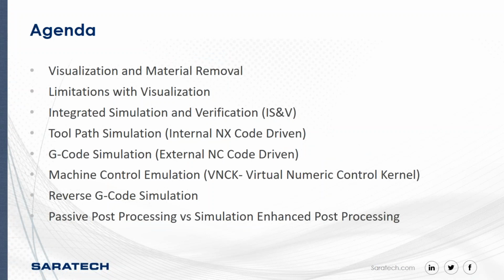We're going to go through visualization and material removal, limitations with visualization, the integrated simulation and verification, which is called ISNV, the toolpath simulation, which is the internal NX code. That is the CLFS file from NX that's driving the simulation. And then we'll go through toolpath simulation, the G-code simulation, I'm sorry, that's external NC code driven from the post